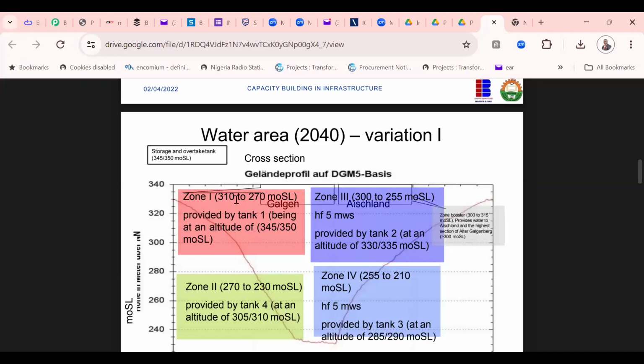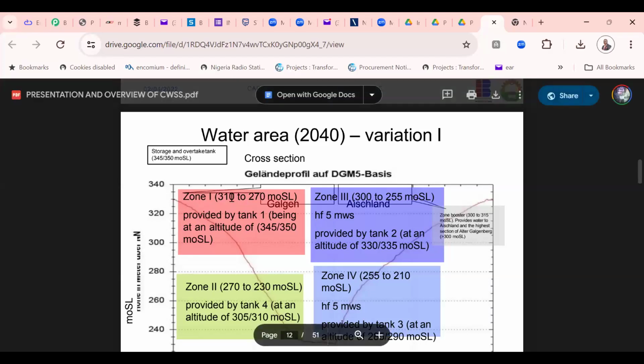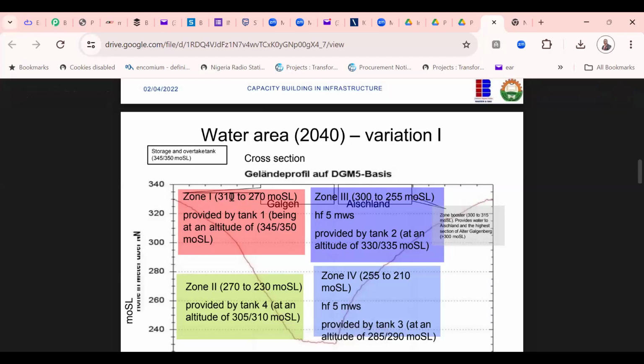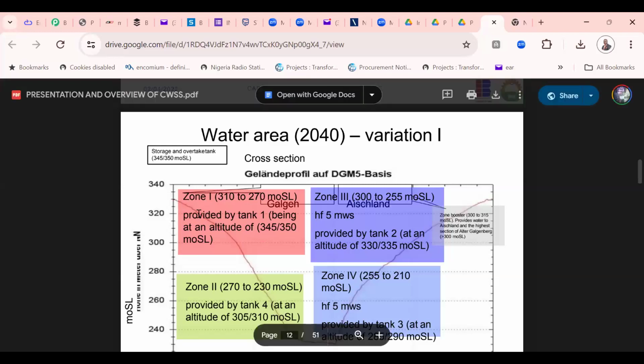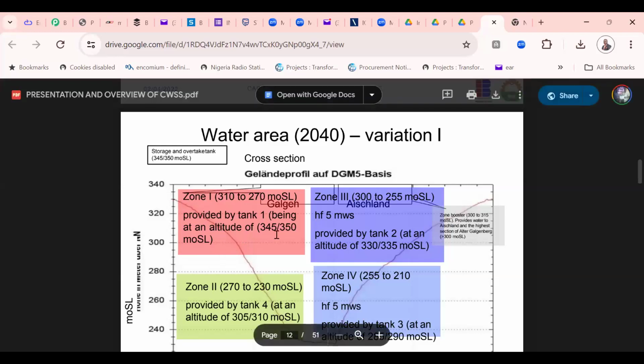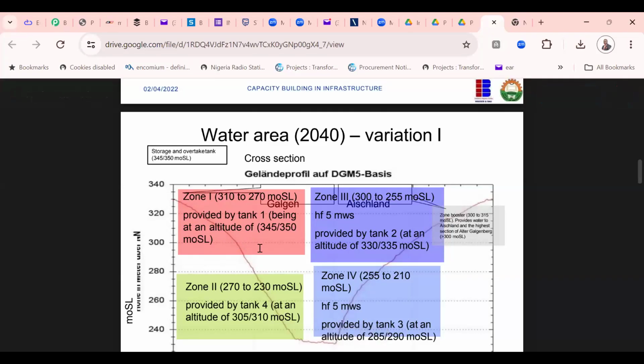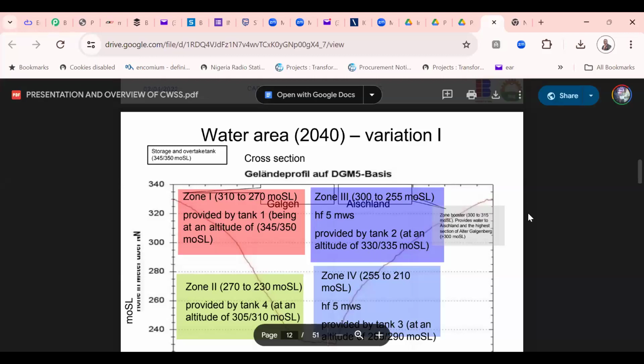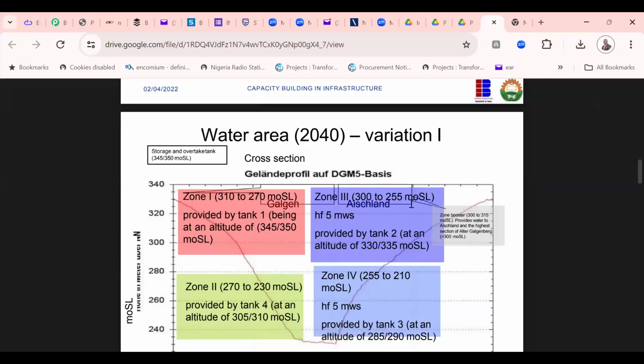So that's enough. And for that 40 bars, using a column of water as 10-meter height, it means the difference of 40 means 4 bars. It means in this zone, I'm sure of, without considering losses, I'm sure of 4 bars. If I put in losses, bend, pipe size, undulation of land, maybe I'll end at 3 bars. So this is good to go.